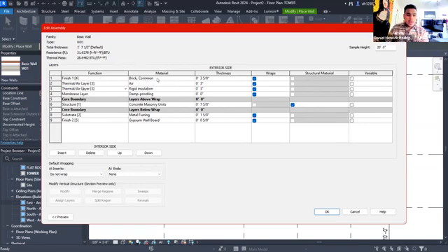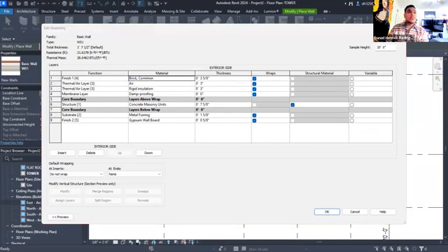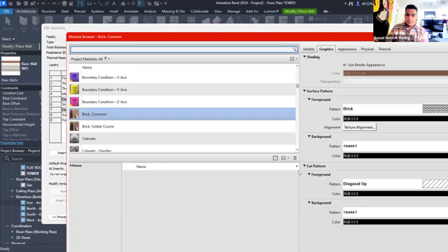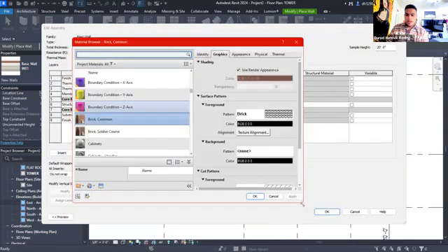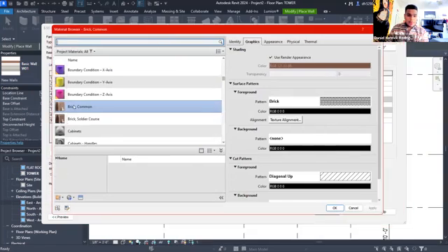Where it says Finish here, Material: Brick, Common, it doesn't show when you hover over it, but you can see this box, and this is the three dots. You're going to click on the three dots. It'll show up when you click, apparently. And when you click on these three dots, this is the window that's going to show up. Oh my, it's really big. Here it is. And it's actually going to have all the properties of the material that we have selected. So I have Brick, Common. You may not have Use Render Appearance selected. You should select it. Your choice, but it just gives the material the basic color that it looks like. So this brick is going to have this color.